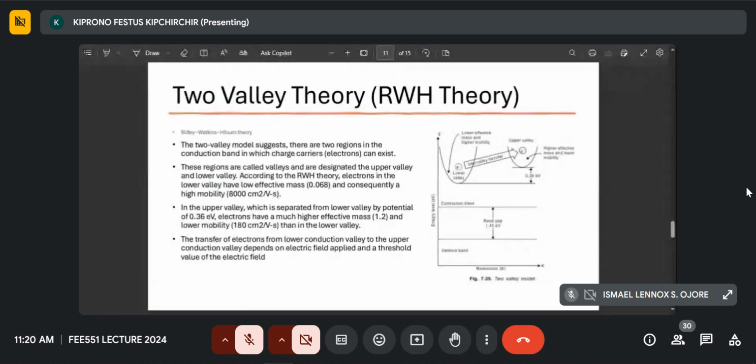If you apply much voltage to a Gunn diode, the current tends not to increase. From V equals IR, for any circuit with a constant R, if we increase the voltage from 10 to 20, the current will increase to retain that relationship. But in this case, as the voltage increases, the current does not increase. As a matter of fact, it decreases. I'll explain the reason later, but keep it in mind because it's part of the basis of the Gunn diode.